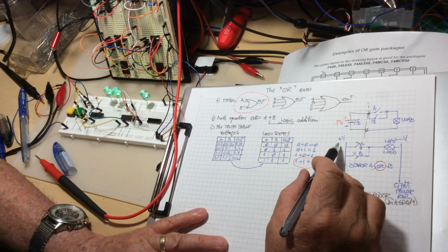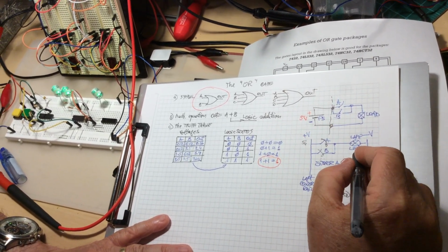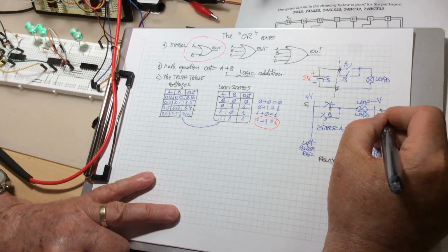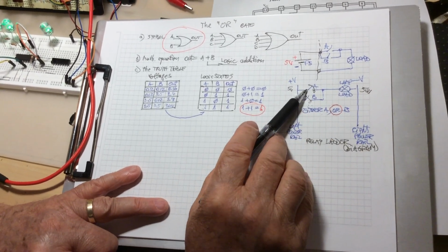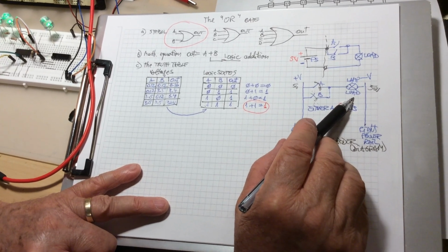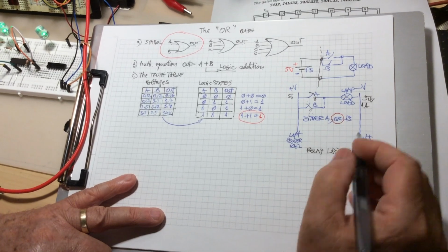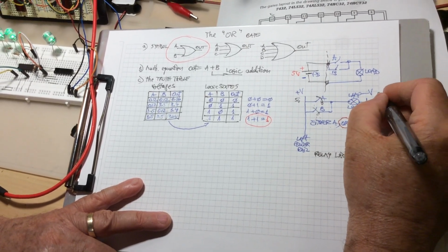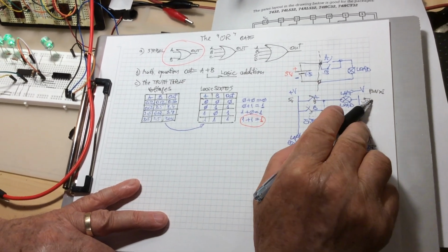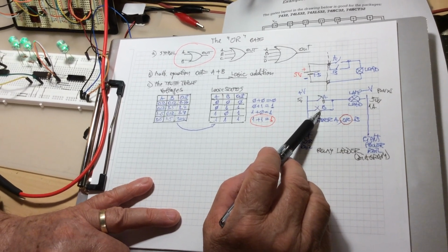For instance, if the voltage here is 5, and the power of the bulb, just to take a hypothetical value here, 5 watts, it doesn't matter if you have one switch on or you have both switches on, it's going to absorb 1 amp. 1 amp here, okay? Simply because, as you know very well, the power is voltage times amperage. So 5 volts times 1 amp is 5 watts. It doesn't matter if you have one switch on or two switches on.